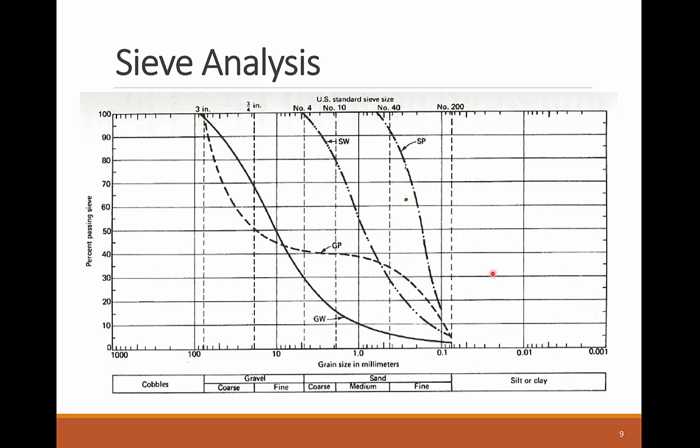The other 2 samples are for gravel samples, namely GW, well-graded gravel, and GP, or poorly graded gravel. The poorly graded gravel is made of only large and small grains, you can see here the change of cumulative weight passing, with no smooth gradation in between, almost flat.